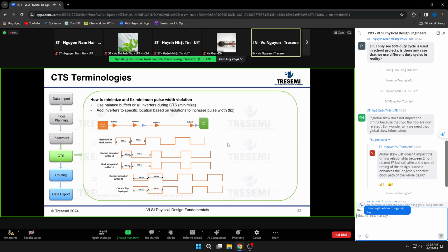And there's a penalty for that, because any time you add a synchronizer, you add more delay when the bus master or bus initiator has to access the downstream memories or peripherals. Hope that answered your question.